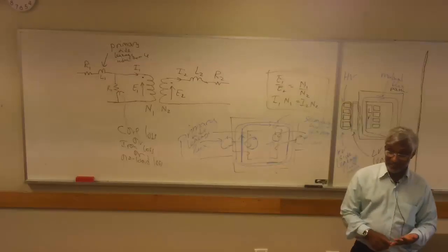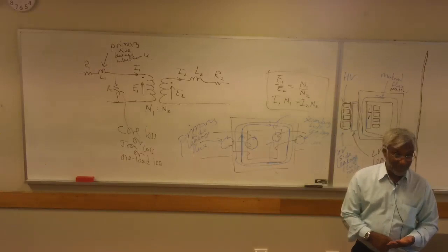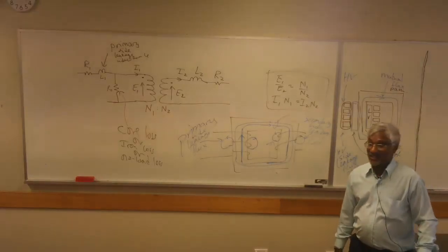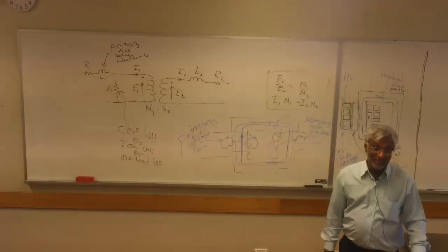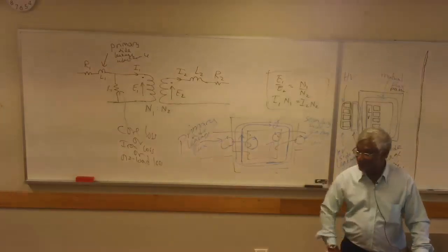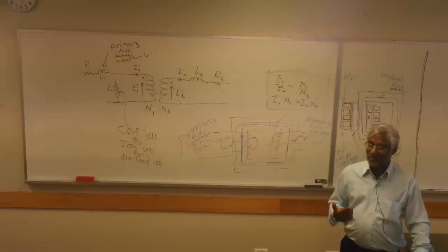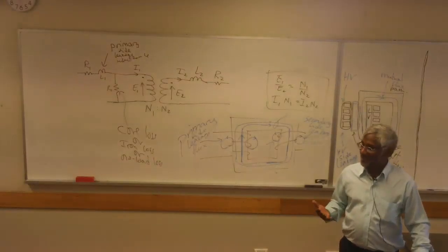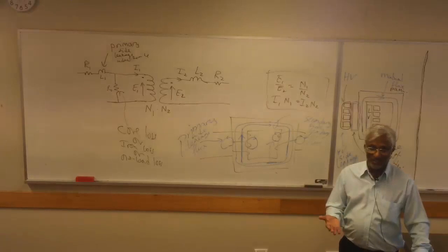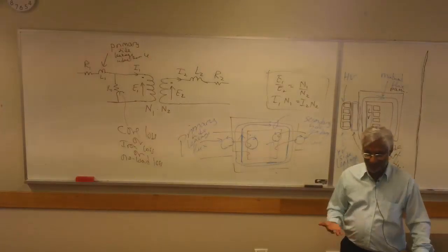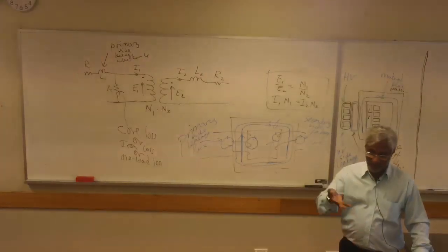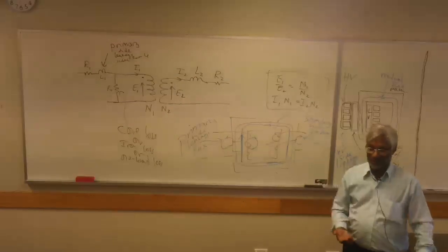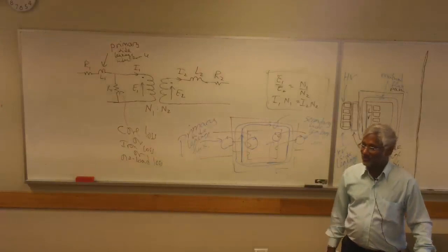So you will be linking magnetizing current with permeability if you realize that you, as an engineer, would probably be trying to get your magnetizing current to come as far down as possible. And in order to do so, you've got to get material with a certain property. And that property is permeability. You would like that permeability to go high and high and high. And if you want your magnetizing current to be 0, then the permeability has to be infinite.